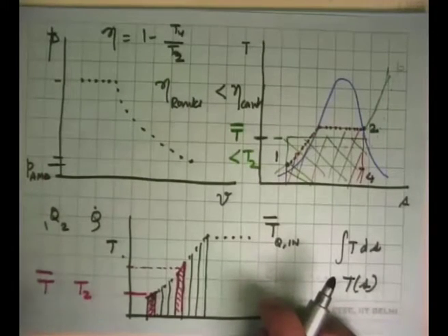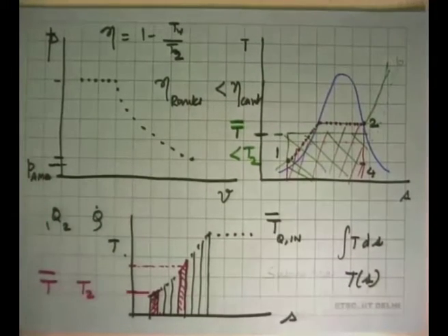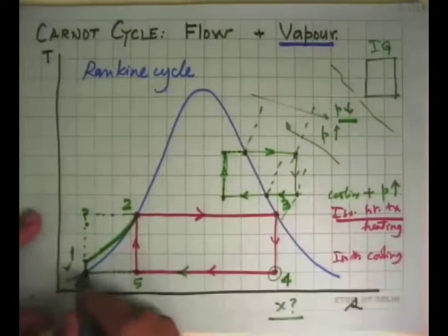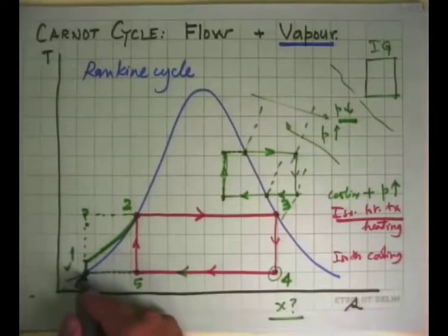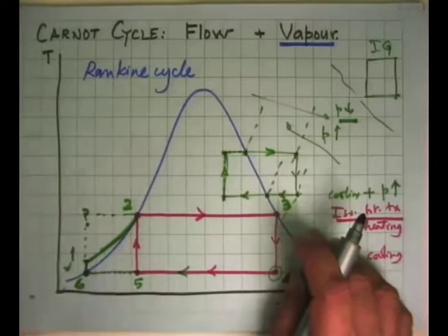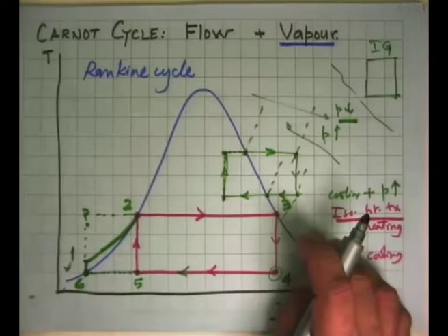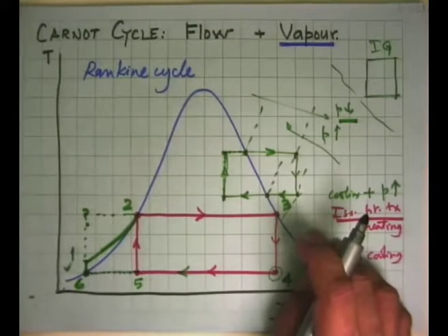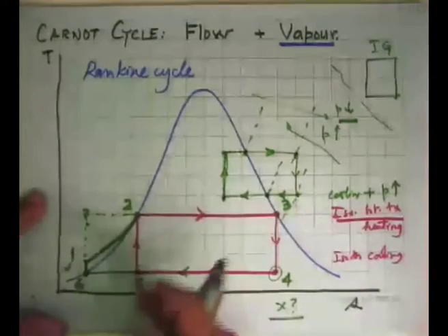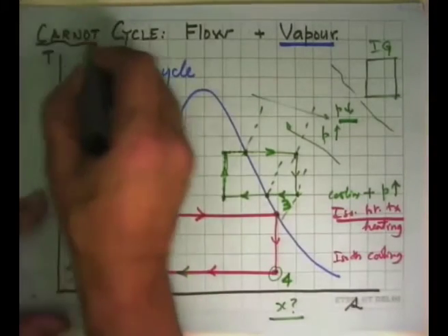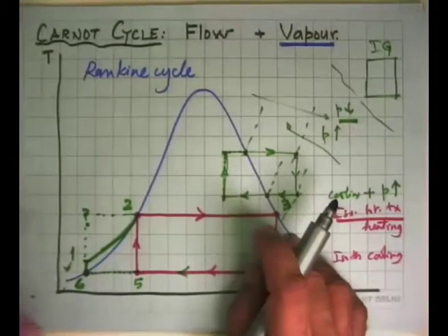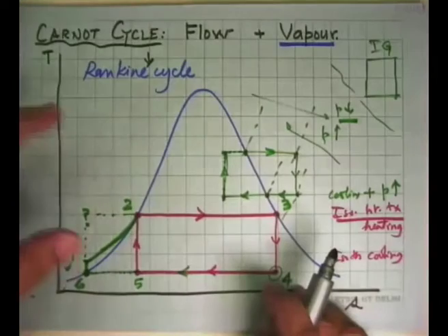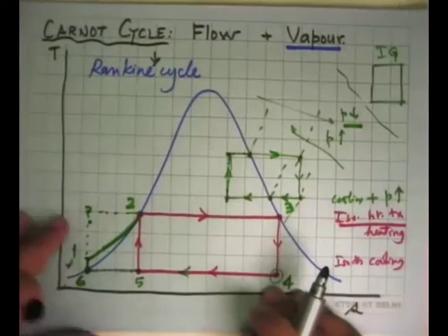We made that sacrifice, but in the process, we have made a cycle which is very close to practically making it. On top of that, there will be irreversibilities of friction, expansion, heat loss, all of that. So the efficiency will be further less than the ideal Rankine cycle. The real cycles will be less. But we moved out from seeing that the Carnot cycle was practically impossible to make, but we said at least in one case, we are able to make a modification here and realize something close to a Carnot cycle.